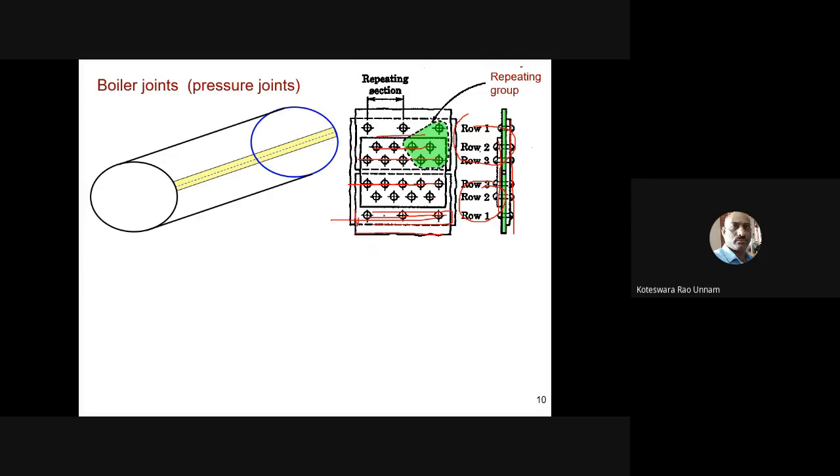So if I go for more number of rivets here, that means I need to drill more number of holes here. Since this point is close to this edge of the plate, it will weaken the joint. In order to prepare any riveted joint, first I need to drill the holes in the plate. So the plate will become weaker and weaker because it is the edge where you are applying the load. Here this is the location which is close to your load application.